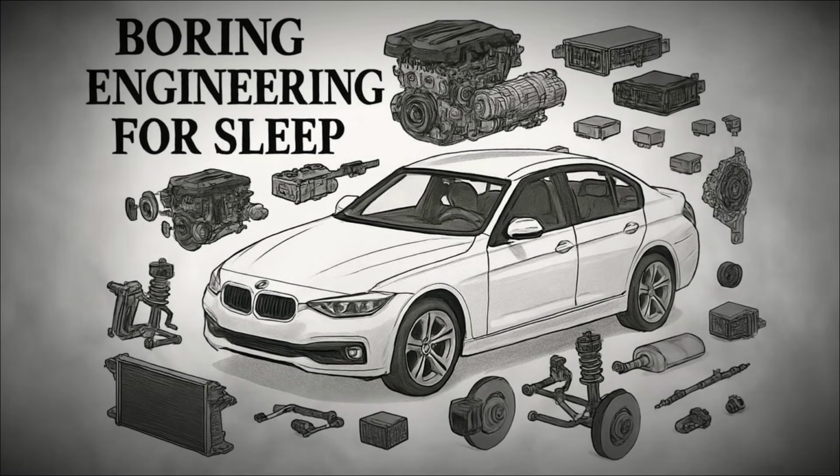A car with worn shocks or broken springs may lose tyre contact with the road, reducing braking ability and steering response. In emergency maneuvers, the suspension helps distribute weight evenly so that all tyres can grip effectively.